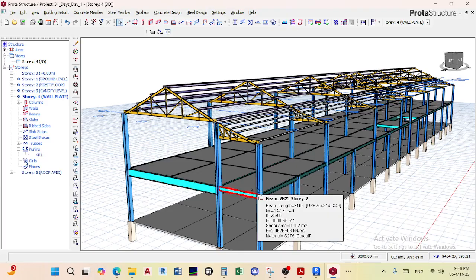So, to begin with, the first thing that you need to factor in, that you need to think of, is the material. If you're going to be using concrete, then you need to have shorter spans. From primary to primary, I would recommend not, according to the BS, could be different, but for me personally, I use 3.5. And also when I'm talking about maybe 200 by 400, 200 wide, 400 deep columns.